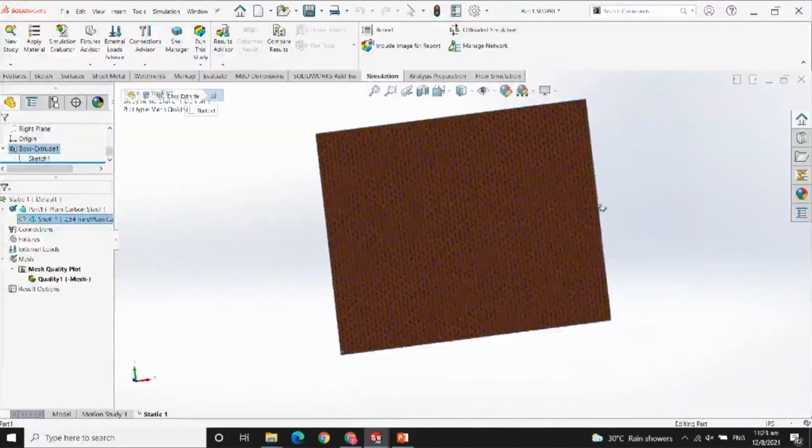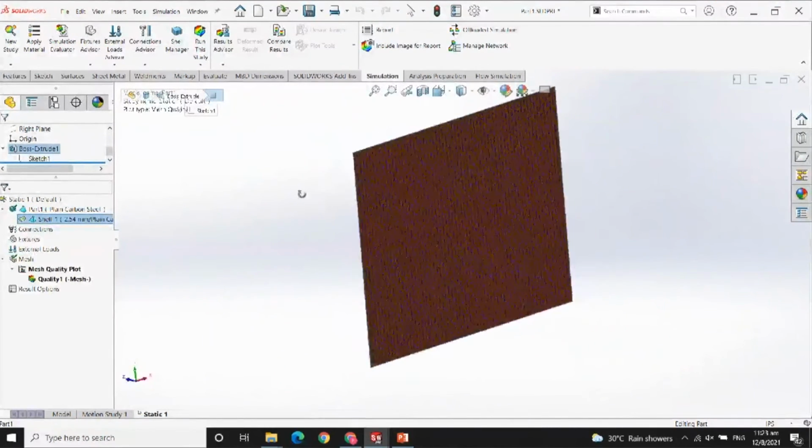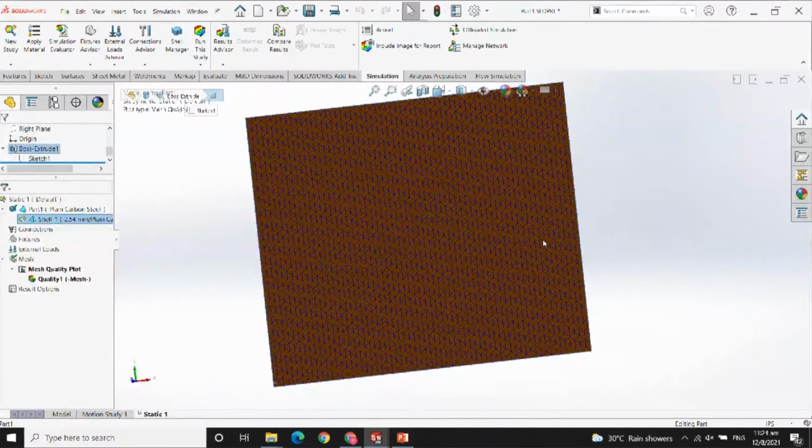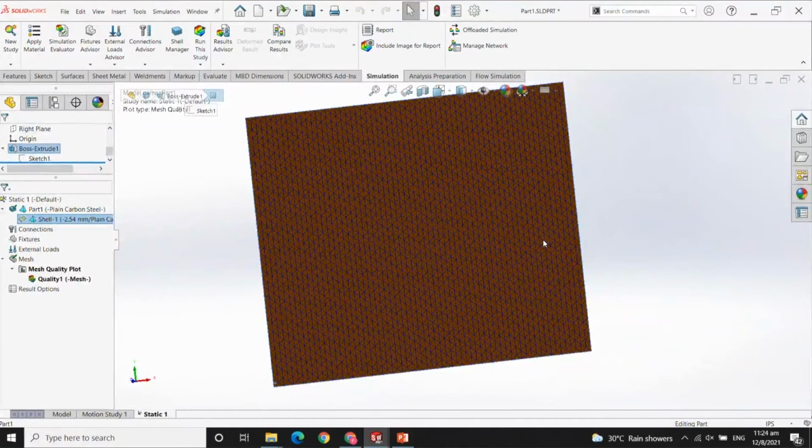As for the reason why we don't want to use the solid element for this part: for simple geometry it is still okay, but for very complex geometry, of course we can use the solid element, but it takes a very long time to run the simulation, and the more elements we have in the project, the more errors that can occur.